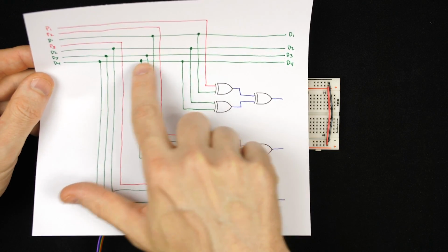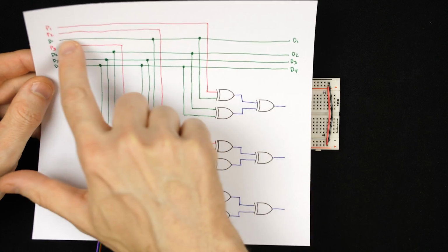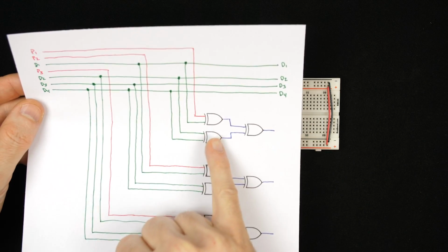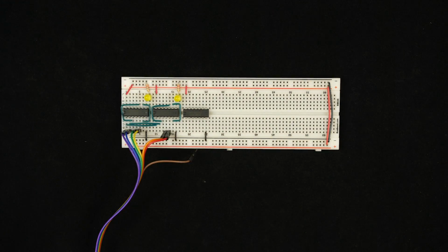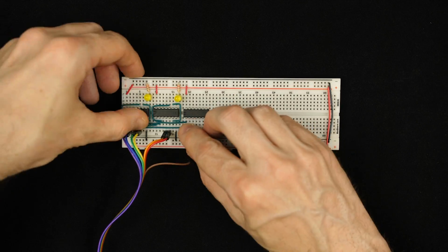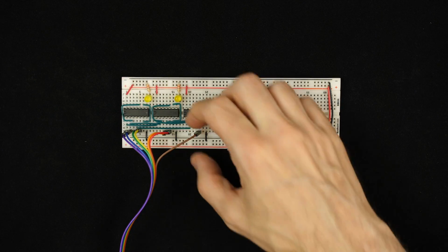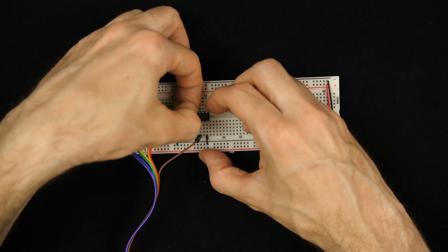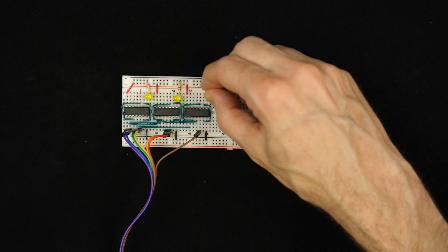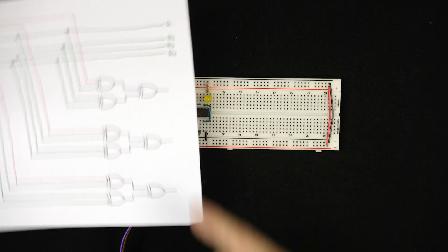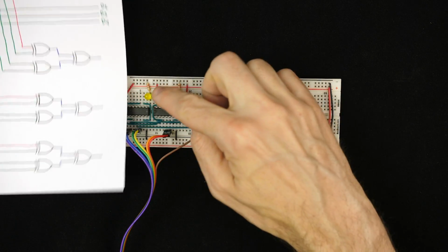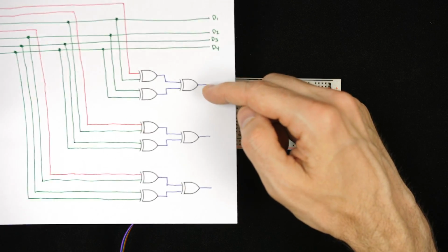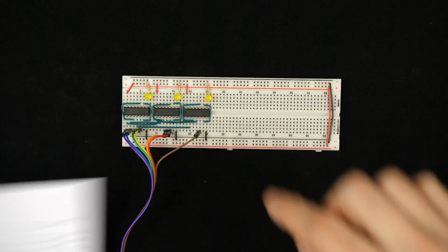It's going to those same 2 inputs there, and then these 2 inputs here. So lastly, we'll do this one, which is just going to look at every other input. All right, so that's every other bit being input into those 2. And again, we'll take the outputs of these 2 XOR gates around to the 2 inputs of an XOR gate on the top, and hook an LED up to that one. So there we go. Now we will get an output on these 3 LEDs to show us which of the 3 parity bits, if any, is incorrect based on the input that we've got.